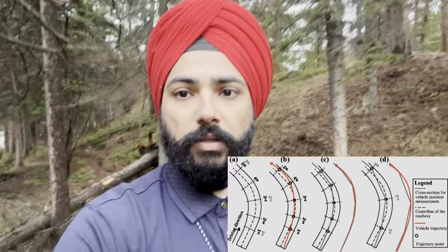And of course, I did a lot of math beforehand, implemented that in Python, created a bunch of plots, and this is not at all plugged in the vehicle, right? I'm just looking at, will this logic make sense if I assume certain inputs? And once I was confident that yes, it indeed did make sense, I then went ahead and said, okay, let's now convert this Python code into C++ and plug it into the actual software. So at that point, I know that the algorithm works.